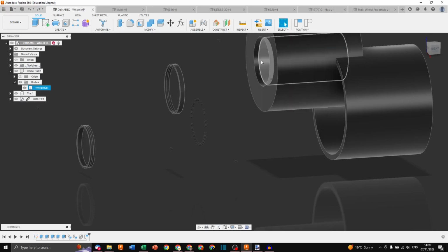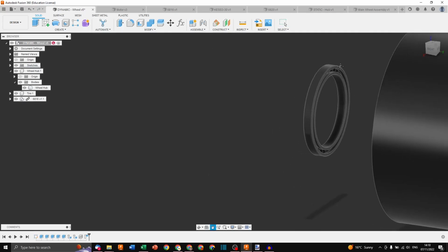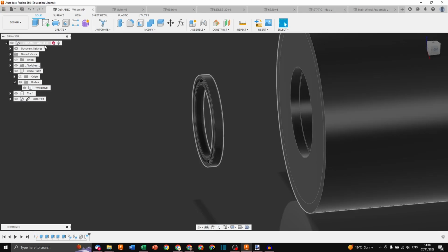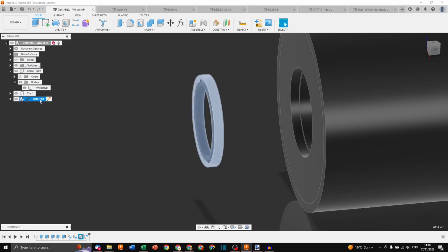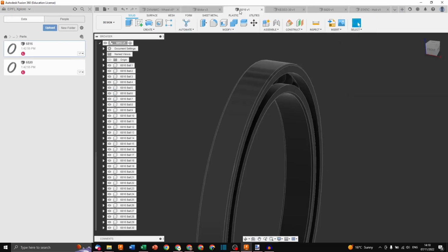It's a powerful option. So I'll revert, and I'll now finally show you how to add a joint origin as we said. So let's add a joint origin to this bearing. Once again, you do not want to be working in the main. This is the main file. You want to be working in the components. So let me work on, okay, you cannot work on imported components. That's a good point. Since I'm working on an imported component, if I want to change this, I should open it up. You can either go back to the Fusion file repertoire and open it up by double-clicking on the file. It's open right here.